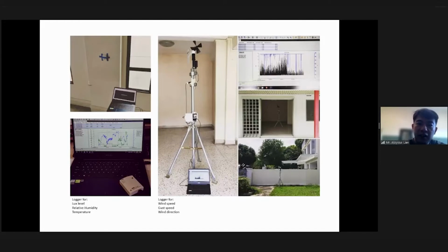very site-specific understanding of the project, because a lot of times, in fact most of the times, when architects design, we will just use the prevalent wind direction that is like from north to south, and then the east-west orientation for the sun. But this may not be the case in Singapore, because sometimes in landed house neighborhoods, we are very close to our public housing, the HDBs.